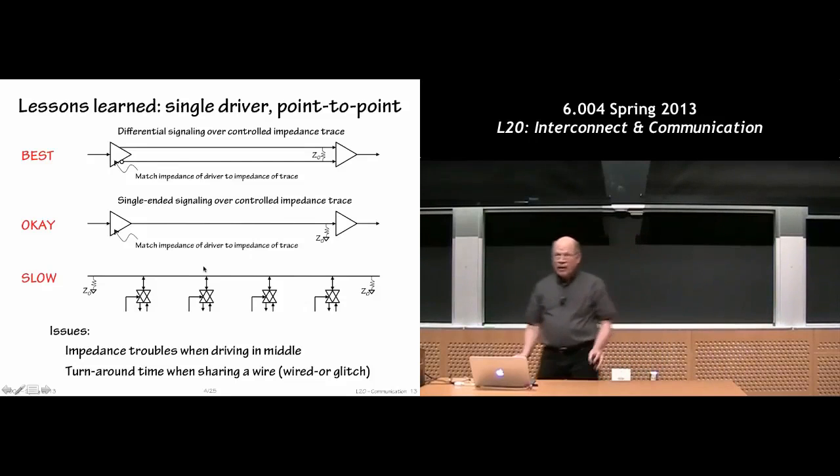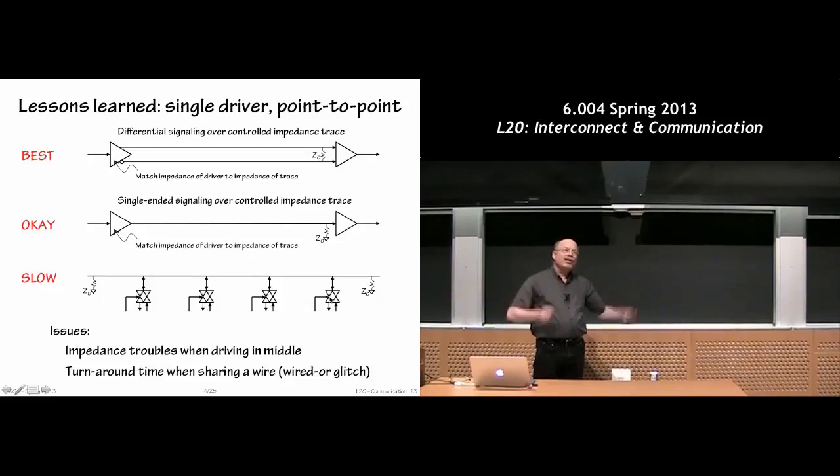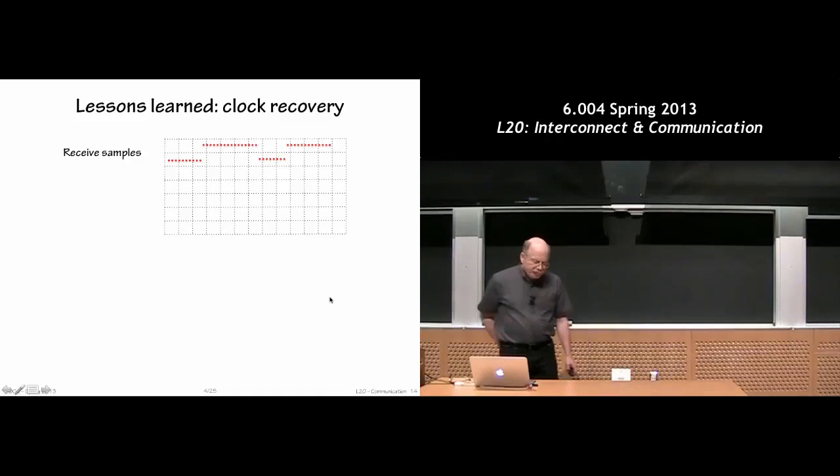So all your voltage steps are half of what you think they're going to be, and it turns out this was just problematic from the start, and the more people understood about the E&M, the more they realized the problems. And then if I switch from this driver driving to that driver driving, in the clean world you can say, well, what difference does it make? He was putting on a 0, now this guy is putting on a 0. But it turned out there were big glitches as the current was being sourced and sunk in different places. So lots of interesting electrical problems.